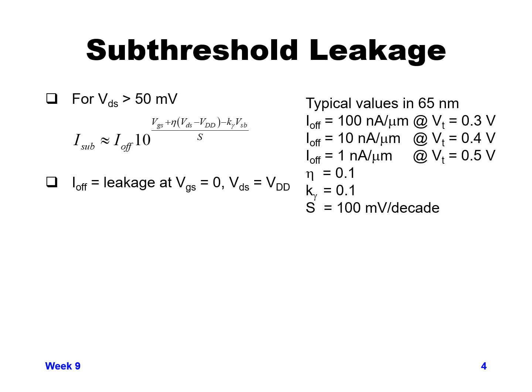This subthreshold equation is true as long as VDS is greater than about 50 millivolts. When VDS is too low, your leakage goes down by a lot, but as long as it's greater than about 50 millivolts, you'll get that equation.